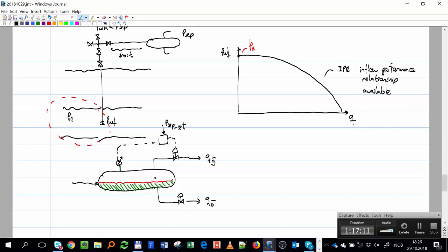I have another system, which is a floater, a level controller. If the level goes up, for example, that goes to another box where I have a level set point, H set, and that's going to move that valve, right?